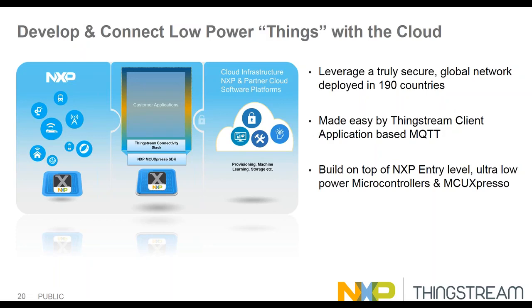But the amount of resources on an LPC 800 is capped at up to 64 kilobytes of NVM memory today. Whereas the reason the Kinetis L was used was because you have scalability up to 256 kilobytes of NVM. So if you wanted to build a slightly richer, more complex sensor node, but still cared about low power, then you could use the L series. But if you cared about cost and simplicity, the LPC 800 would be the best option.